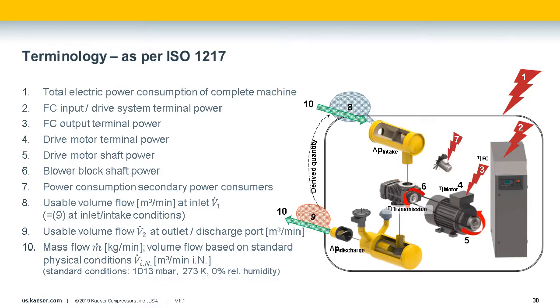But again, any blower package includes both a blower block as well as silencers and these other electrical components. So to get an evaluation of the entire electrically powered machine, we have to advance to what we call Annex C, which will be the entire package. If we put on a VFD, then we utilize Annex E. And with Annex E, we get those 5 data points I referred to before regarding min flow, max flow, and then the points in between.